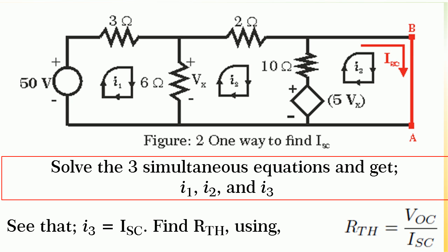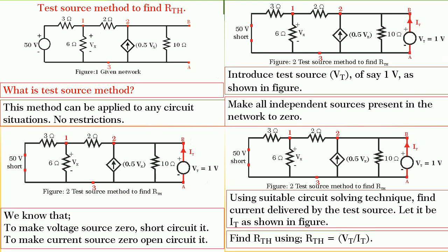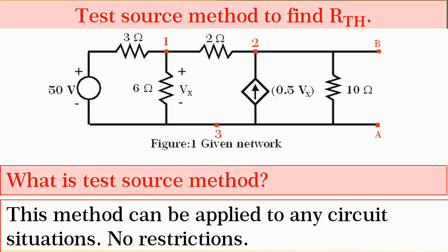Friends, you can solve by this method which I have stated now, but I am going to introduce another very easy method of solving for RThevenin, and that is called the test source method. First let me tell you the procedure of solving for RThevenin using the test source method. First of all, you should know that this method can be applied to any circuit situation. There are no restrictions at all.